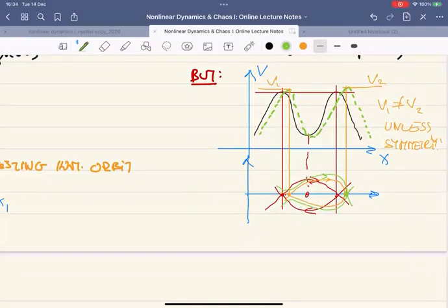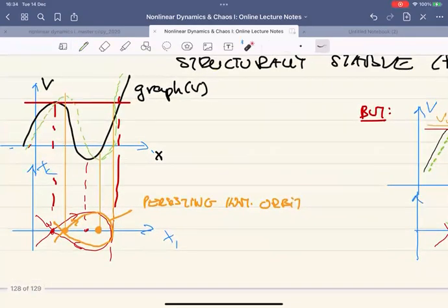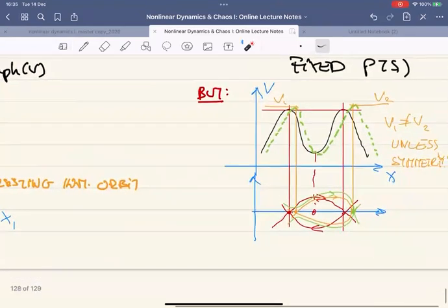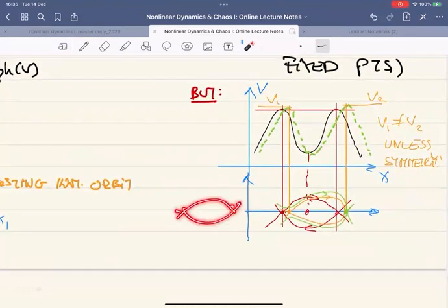Incidentally, that's the reason somebody gives you a streamline plot from a general two-dimensional flow, or you just look at a map, which is level curves of a function. You shouldn't be seeing heteroclinic connections in a generic picture. And indeed, you look at streamline plots. Why? Because in the case of streamlines, the stream surface instantaneously acts as a conserved quantity along those. No matter how complicated the flow is, one sees these all the time, the type of closed orbit, saddle points, homoclinic orbits too, because they are robust. But somebody gives you an instantaneous streamline plot of a non-symmetric fluid, you should not see heteroclinic connections in general.